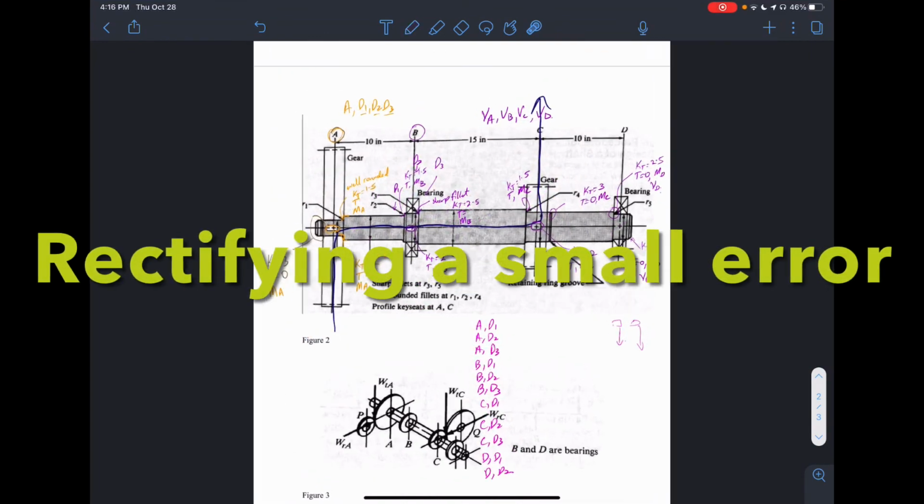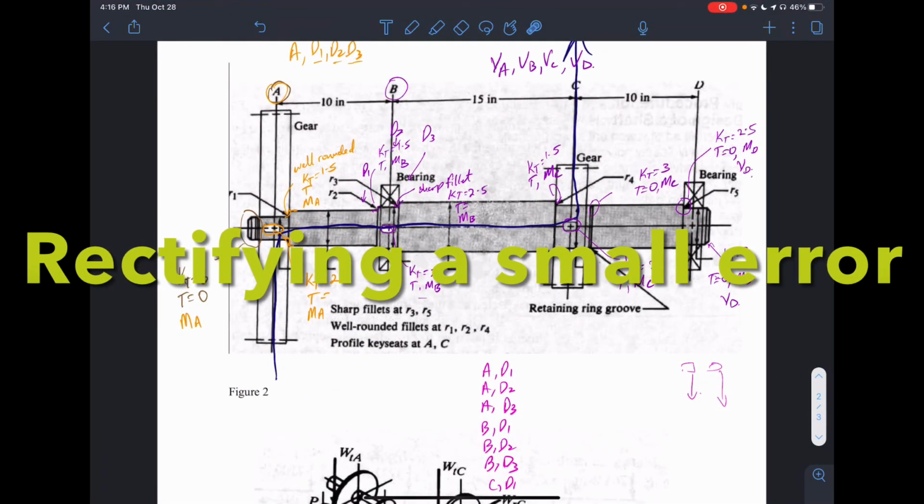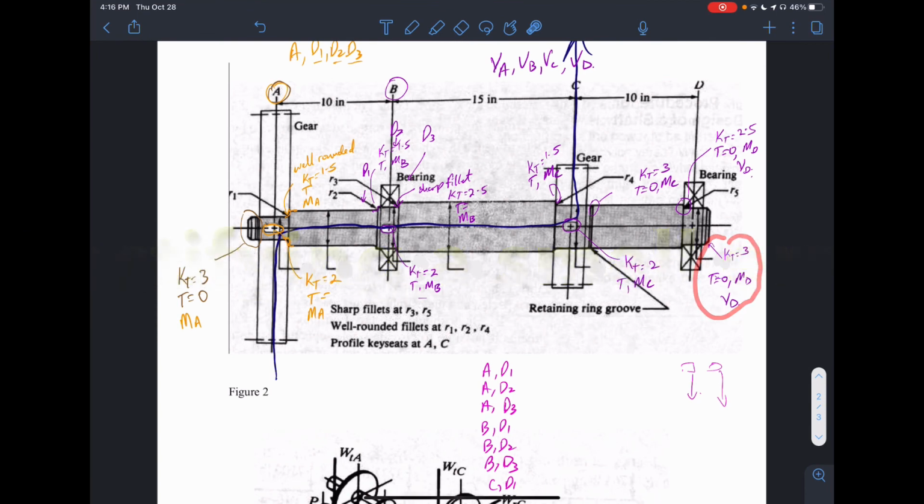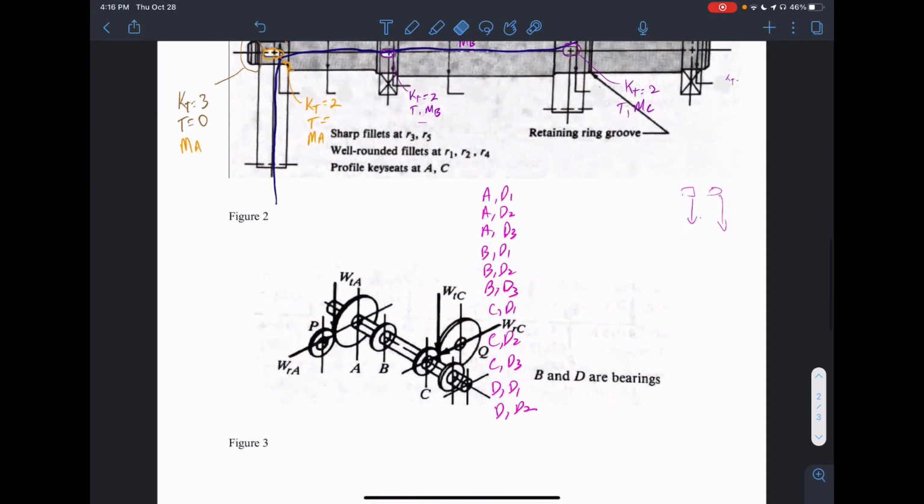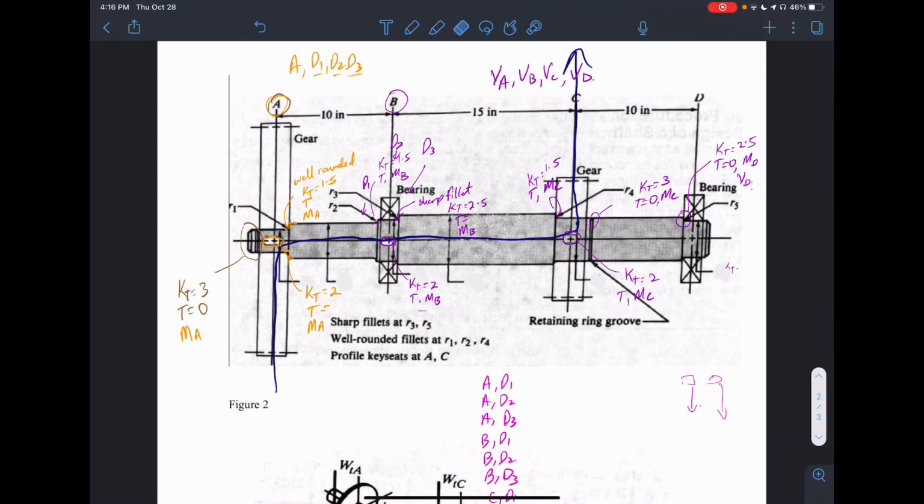Okay, before moving on, I just said that you would have a circlip on the end here to hold the bearing. This is not true. The bearing normally is held on by its tight tolerances. So you could actually remove this last term here. You could also remove DD2. So all we'll be considering is the sharp fillet here.